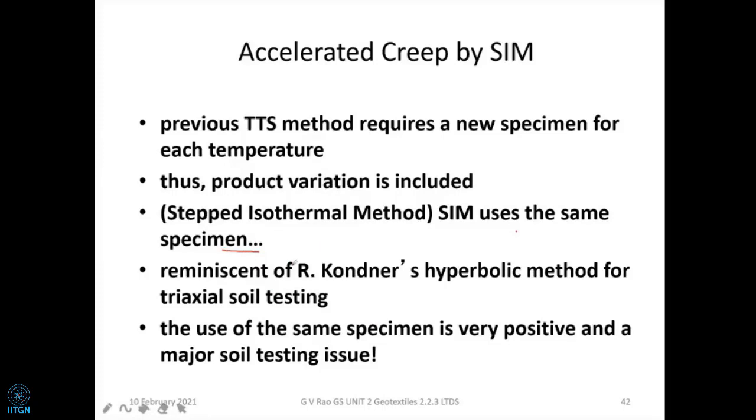Do you know that there's a triaxial method of estimating the failure value based upon the stress-strain curves at higher pressures? I think maybe I'll teach you some time, or ask madam, or you've done it already. There's a hyperbolic method of estimating the result. What do they do? Supposing we conduct the triaxial test at a given confined pressure up to 2% strain only. From this, we can predict the failure value by using the hyperbolic law.